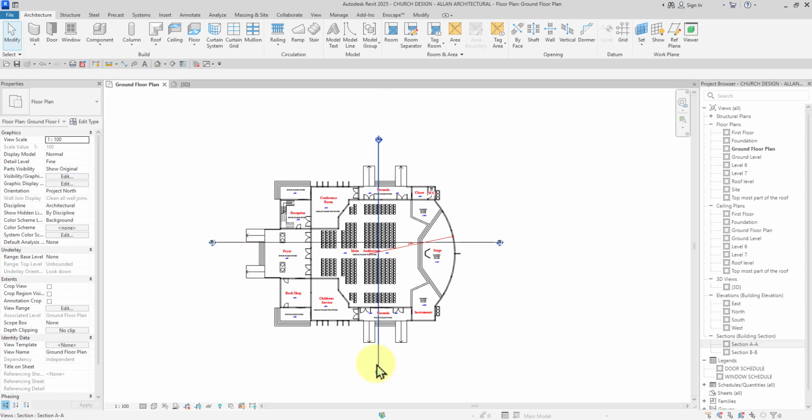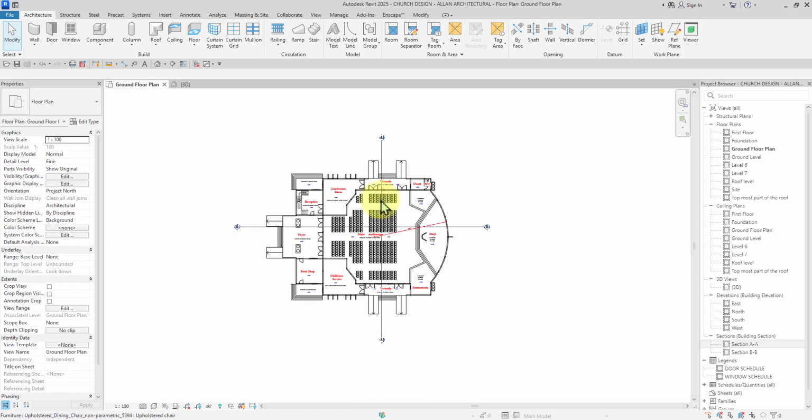If you are watching this video by now, I believe you should know how to cut a section, because I previously taught that in the old working drawing series. You just click on this tool right here, and then you cut your section in your drawing at any part that you want. Anywhere that you would want to show more detail, you'd practically have to cut your section there.